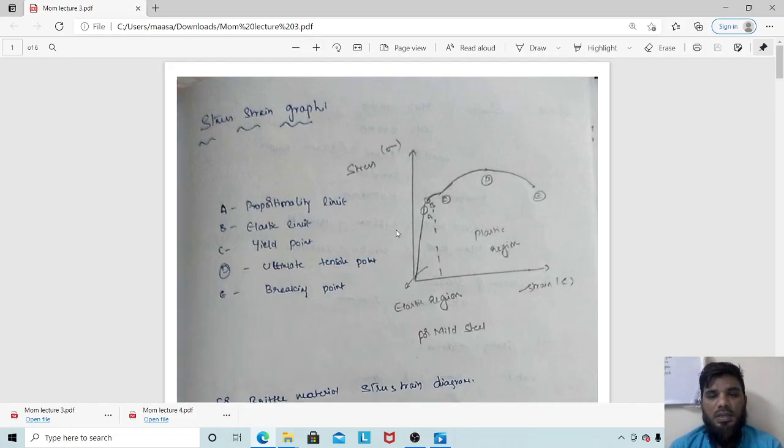In this, generally what we do is we take a material and apply a continuous stress. When you are applying a stress, obviously because of the stress, a small deformation is produced. Initially, as per Hooke's law, in many ductile materials, when you apply the stress, a strain is generated. Up to some extent, the stress and the strain will be directly proportional to one another.